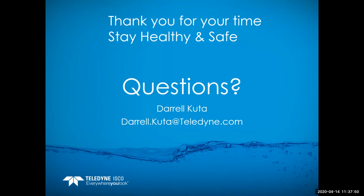Now, another question that came in regarding the Doppler sensors is, what happens if the pipe goes full, if it's surcharged? Well, you're still going to get accurate flow readings, because when the pipe goes full, the level transducer is going to recognize that the pipe is 100% full, so our area is going to be at 100%, and then at that point the flow rate will be proportional to velocity. So you continue to get accurate flow readings, and it can read the reverse flow if it starts going backwards.